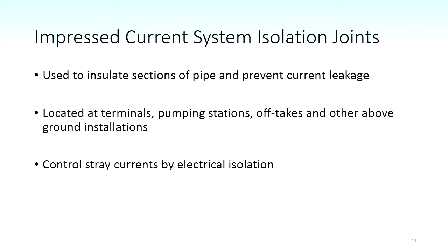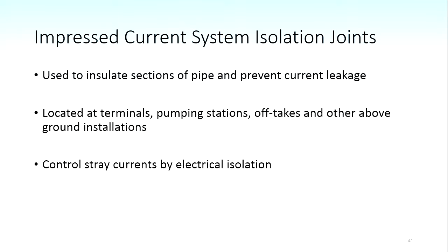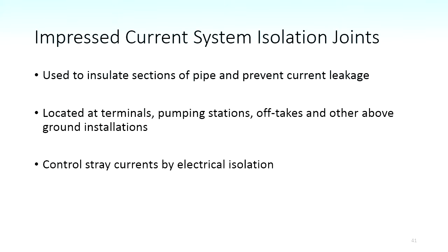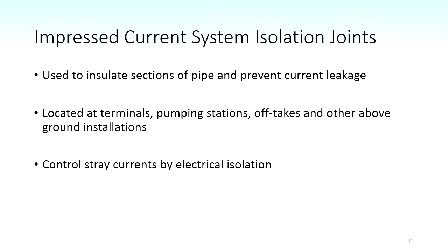What you've got on your handout is this plot, which at first sight looks a bit complex. Sorry, again, it's black and white, so you might want to make some additions to it. So this green line is your current on. The blue line is the current off. The red line is your protection potential, minus 850 millivolts. So this is the protection potential you want. And you can see that at times, at certain distances from the test point, the potential is not cathodic enough.